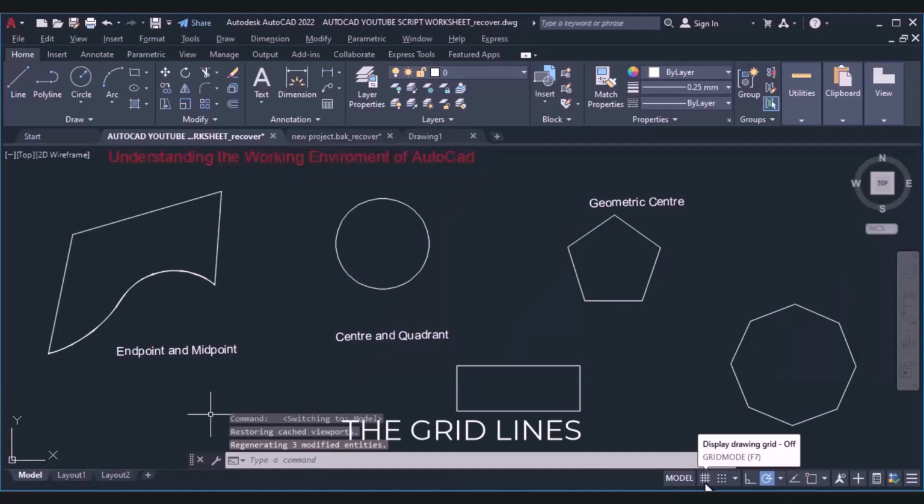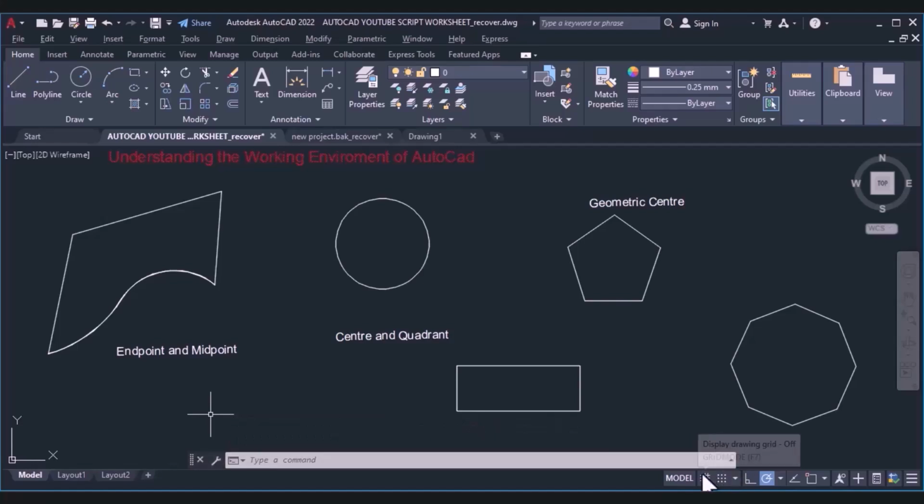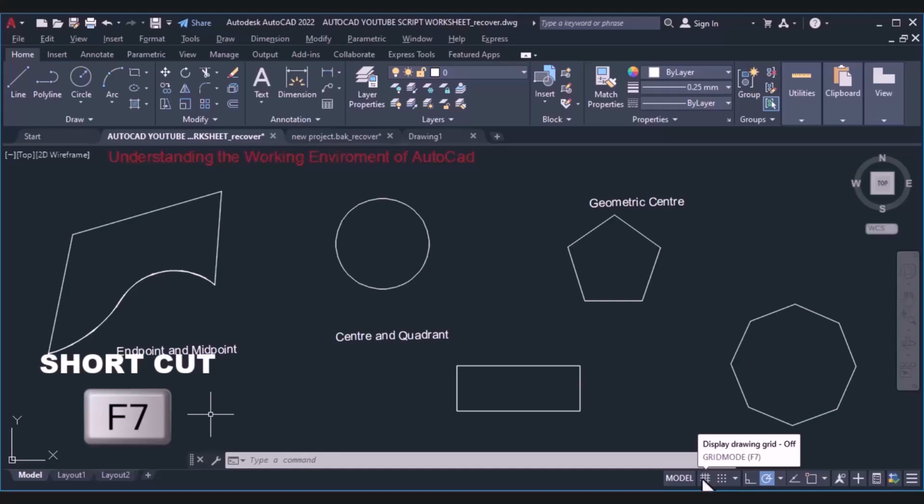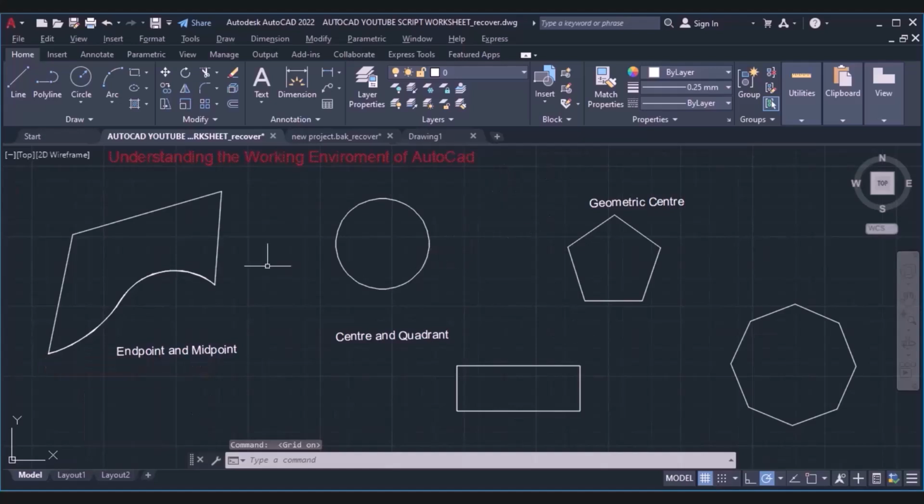Now the grid lines, when activated, help bring out the grid mode. It can be activated either using the shortcut F7 or just by clicking on this status bar button over here. Notice when I highlight it, notice the lines. These are called the grid lines. These lines are spread out all through my workspace.